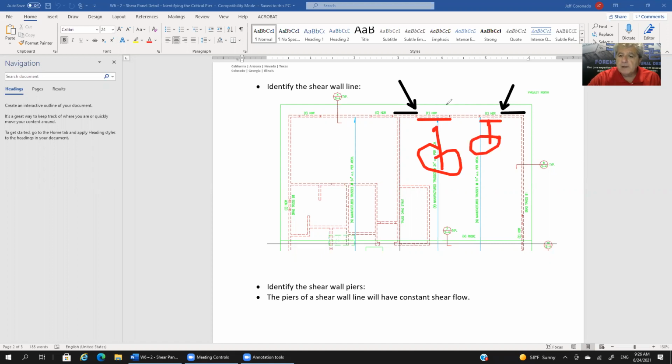So that means that the amount of resistance that we have at this end is not only the weight of the roof over the wall plus the weight of the wall itself, but it's also the amount of roof over this beam that is going to participate in keeping this end from lifting up. By extension, this beam, this header, brings in this amount of contribution from the roof to resist that uplift.